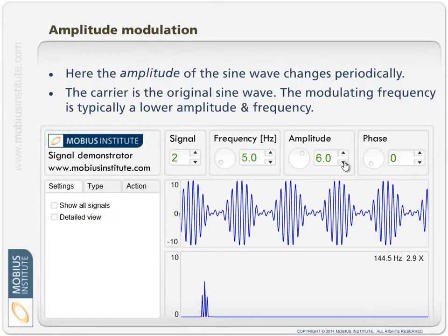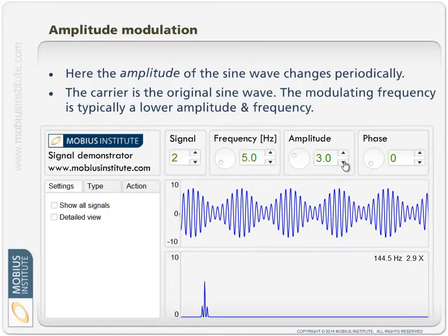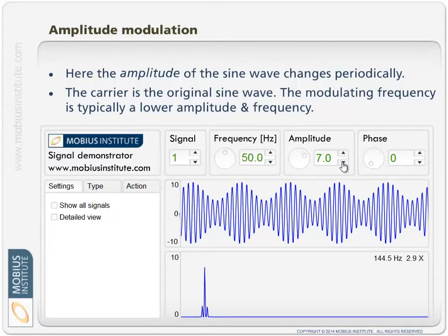And I notice the time waveform starts to look a little bit odd, but same way if I increase the carrier signal, then sure enough the center peak goes up. And if we played around, I could make the center peak completely go away and just have sideband peaks. In reality, we can have a situation, a little bit hard to explain quickly, but you get sort of this addition and cancellation of signals such that the sideband amplitudes aren't the same. We can get a little sideband peak on this side and a much bigger sideband peak on this side.